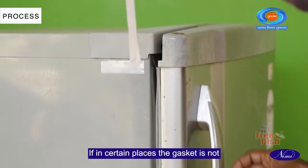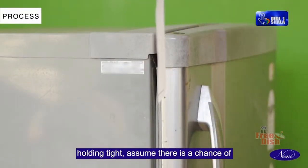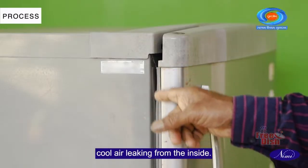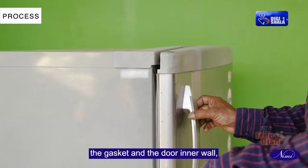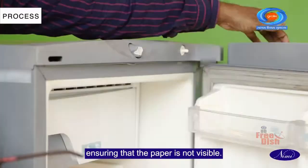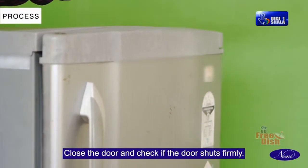If, in certain places, the gasket is not holding tight, assume there is a chance of cool air leaking from the inside. Fold the newspaper neatly and insert it between the gasket and the door inner wall, ensuring that the paper is not visible. Close the door and check if the door shuts firmly.